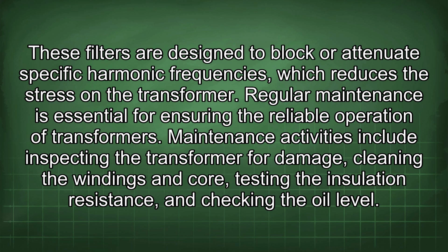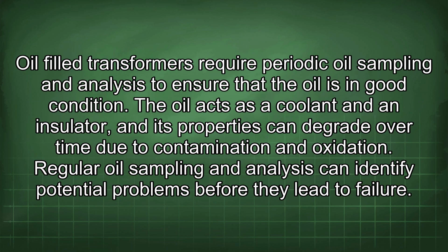Oil-filled transformers require periodic oil sampling and analysis to ensure that the oil is in good condition. The oil acts as a coolant and an insulator, and its properties can degrade over time due to contamination and oxidation. Regular oil sampling and analysis can identify potential problems before they lead to failure.